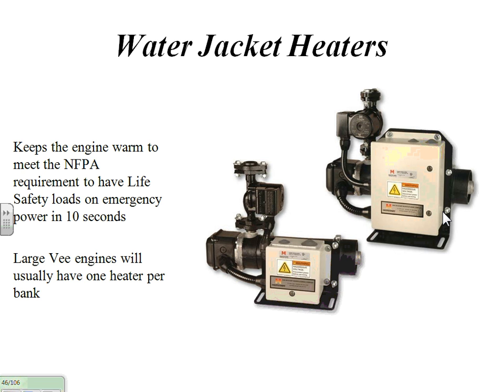Enclosures are very important because we have to keep that engine warm. Part of NEC and NFPA is a requirement that emergency generators start and be online supplying power within 10 seconds.